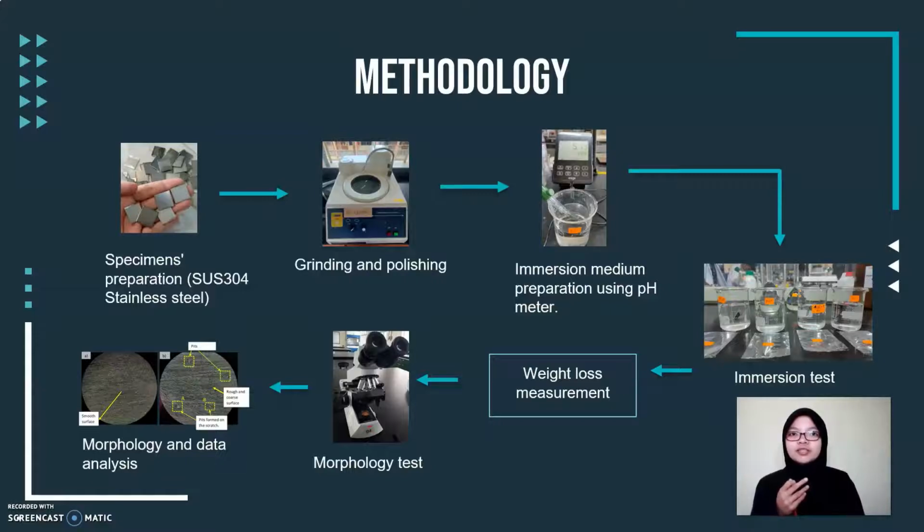For pH 7, pure water was used in this experiment to evaluate the corrosion rate. pH 9 was prepared by adjusting the pH of the alkali solution used in this study, which is 0.1 mole NaOH solutions. To obtain different pH of corrosive media, a pH meter was used to make sure the desired pH values were accurate.